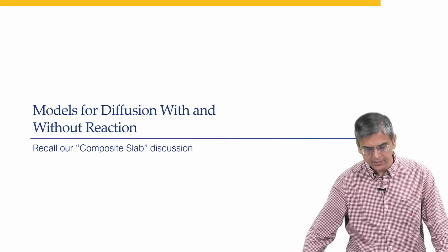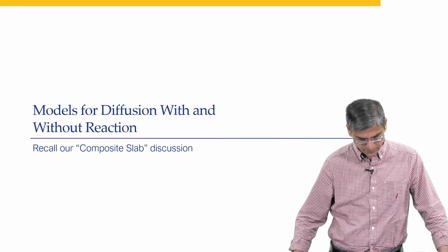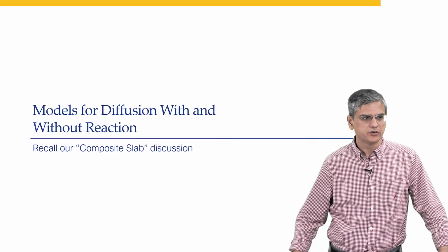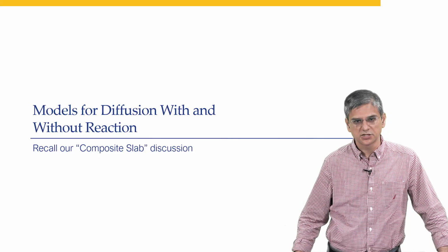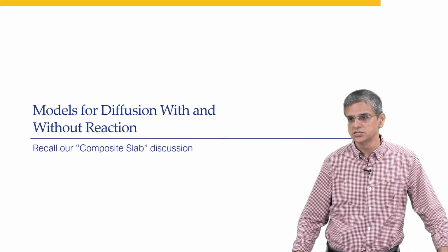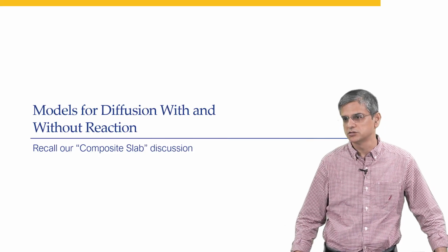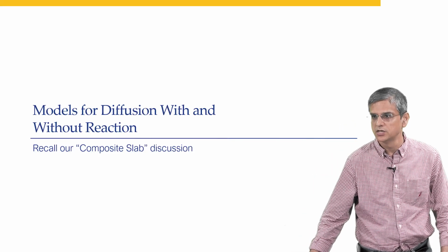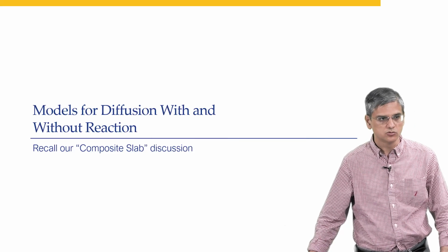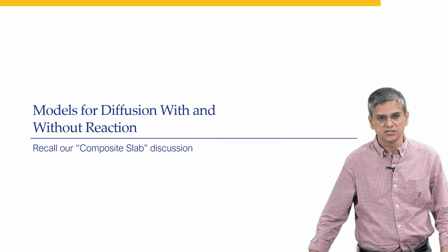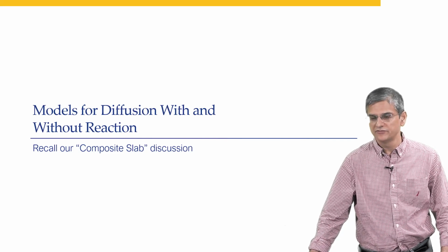So, welcome back, and we'll get started with where we left off in the previous lecture. What we were doing is basically looking at reactions in non-catalytic solids. So, it could be, say, solid dissolution, it could be ore processing, it could be catalyst deactivation or decoking in order to reactivate the catalyst, or it could be solid burning, various different cases.